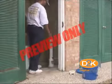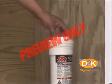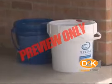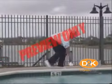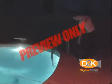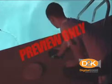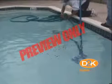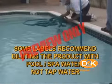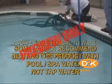3. Add chemicals to plenty of pool or spa water. Chemicals should be applied directly to the pool or spa water through a suitable feeder, pre-dissolved in a bucket of pool or spa water, or distributed across the surface of the water according to the manufacturer's directions. Hand feeding of chemicals through the skimmer is not advised, unless label directions specifically state skimmer application. Some labels recommend diluting the product with pool or spa water or pre-dissolving granulated products in a large quantity of pool or spa water, not tap water.